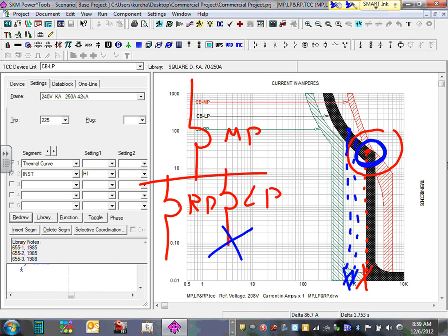How do you solve this problem, guys? Everybody can see that. And the second thing, if I have a short circuit on the receptacle panel, which is right here, the one that's going to trip is the receptacle panel, right? You don't want the main to trip at all. You just keep them all at low then. When they're at low, they're fine. Yeah, you can put them at low, and that's what we do.